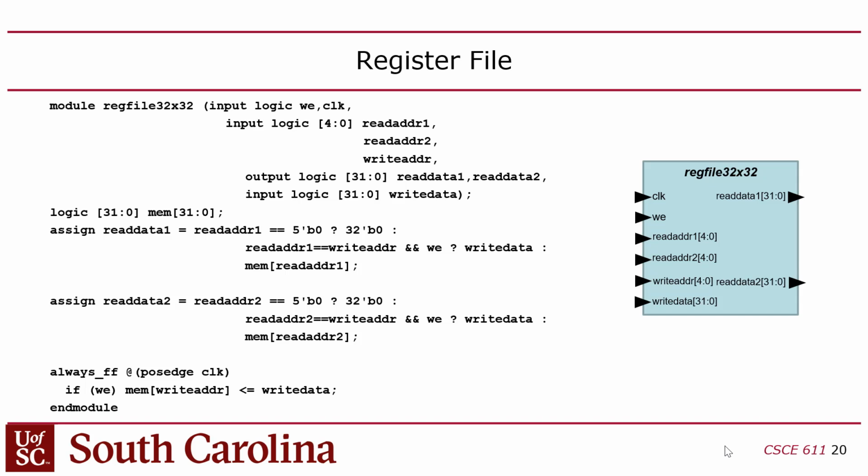Pretty much all of them, right? Almost all of them. Almost every instruction results in the writing of a register. The ones that don't are branch instructions. If you do a branch or a jump instruction, then you're just changing the program counter essentially, right? You're not changing one of these general purpose registers, register 0 to 31. So branch and jumps don't change a register, and store instructions don't. Not that we're implementing those, but a store instruction writes to memory, and that doesn't change a register.